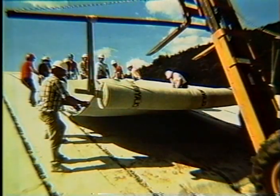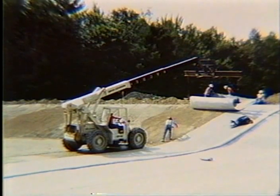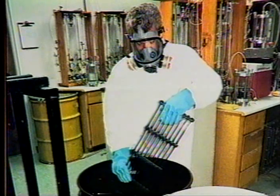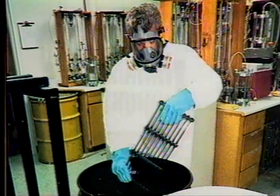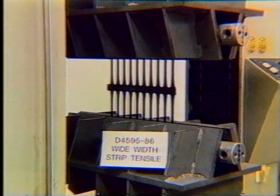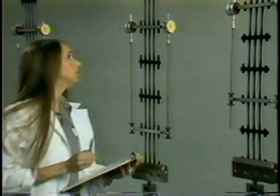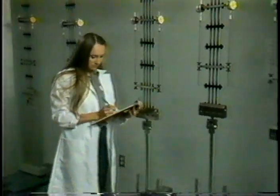On very steep slopes, it is difficult to place the soil component of a composite liner. A GCL, which can be rolled down more easily, may be used instead. The geogrid, as all the other geosynthetic materials in this liner system, must be resistant to chemicals in the site leachate. Candidate geogrid samples should be assessed for their tensile strength. They must also be tested for their resistance to long-term creep, usually over 10,000 hours.